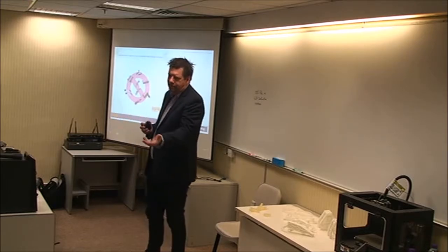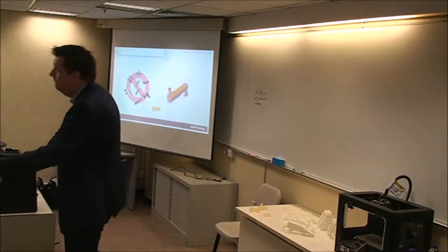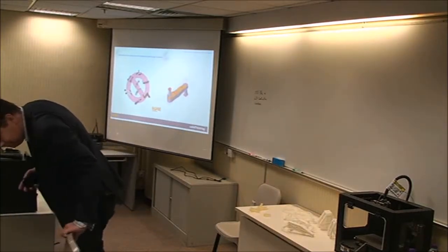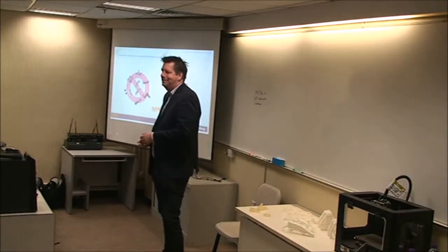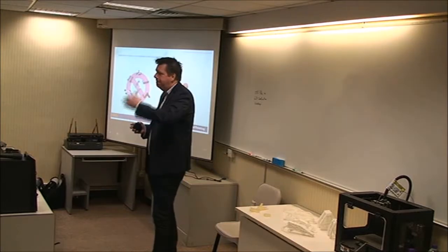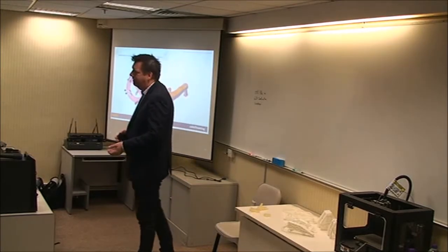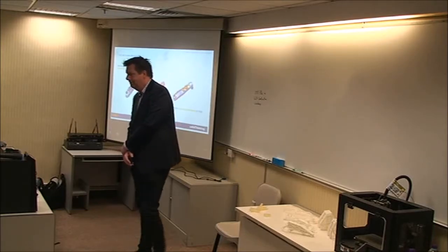So things like a plastic chair, you might have your custom surface at the front. You can't touch that. You can fill the back end with designable material. That doesn't have ribs on it, but the topology optimization can tell you where to put the ribs. So again, that customer surface, don't touch. Design freedom. What do you do in the background to make it structurally good?